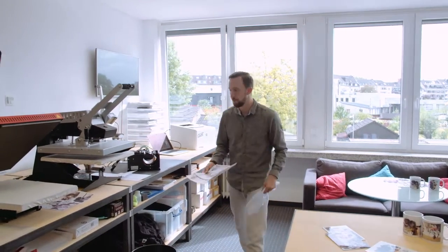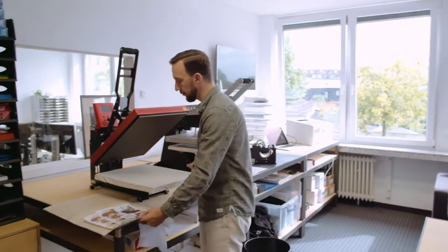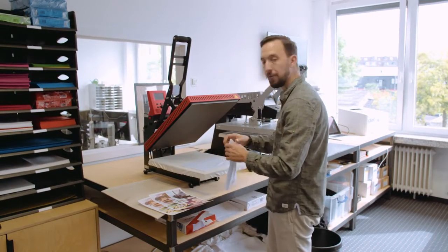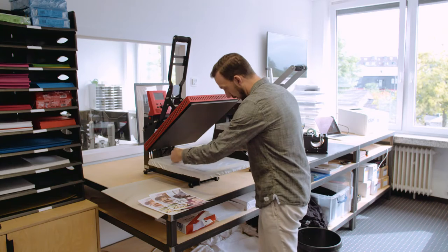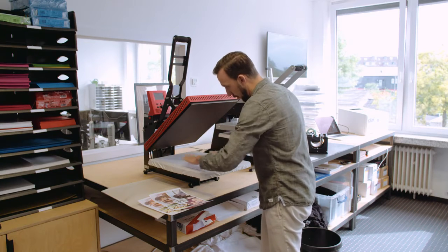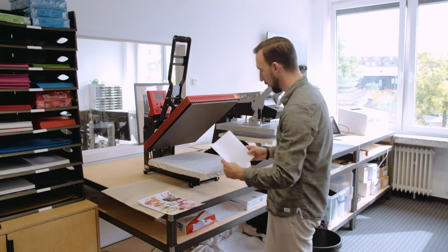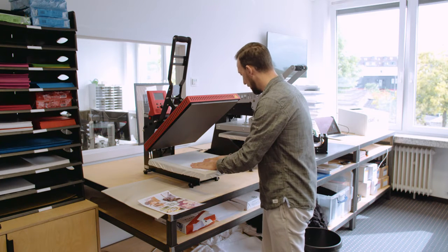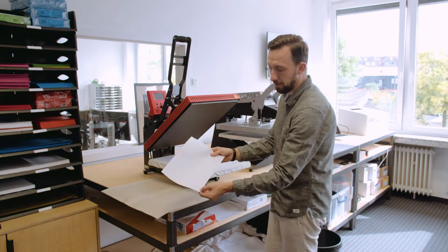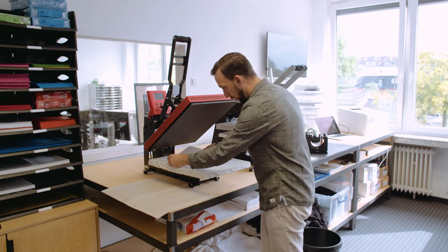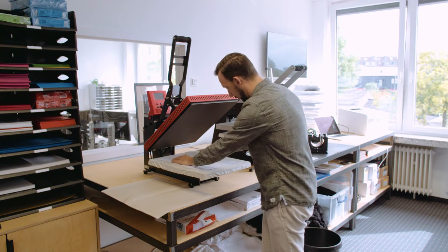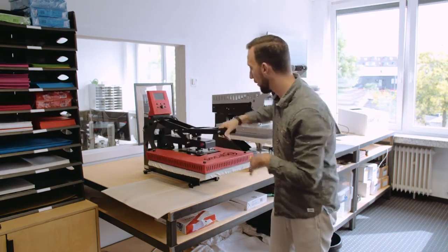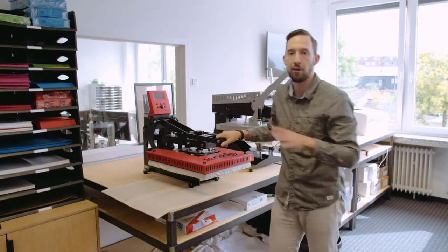So we go over to the heat press. The heat press is preheated to 200 degrees, and I'm going to place two polyester fabrics, an identical type of fabric, on the bottom plate. Careful not to burn my fingers. I'm going to use the file which was printed without the profile on the bottom one, and the one that is marked ICC on the top one. That doesn't make a big difference because this is a good heat press. It's very accurate in temperature and pressure all the way. And I'm pressing these two together for 60 seconds at 200 degrees.